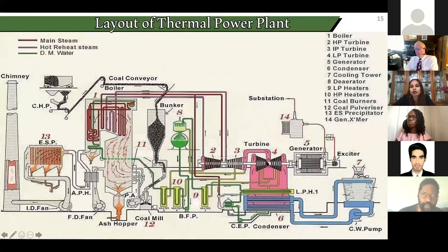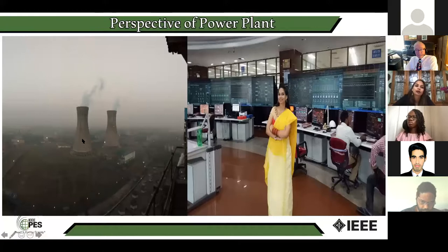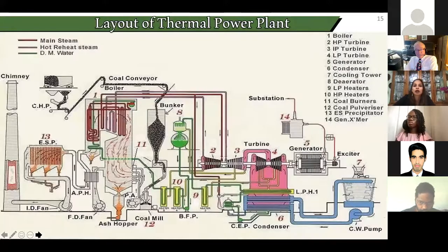And then when the steam condenses and finally relaxes to form water in a closed loop cycle, the water goes back to the cooling tower that I showed you. To cool the steam that we have produced, we need a lot of cooling water, and that cooling water actually helps to cool the steam and get the cycle rotated back.